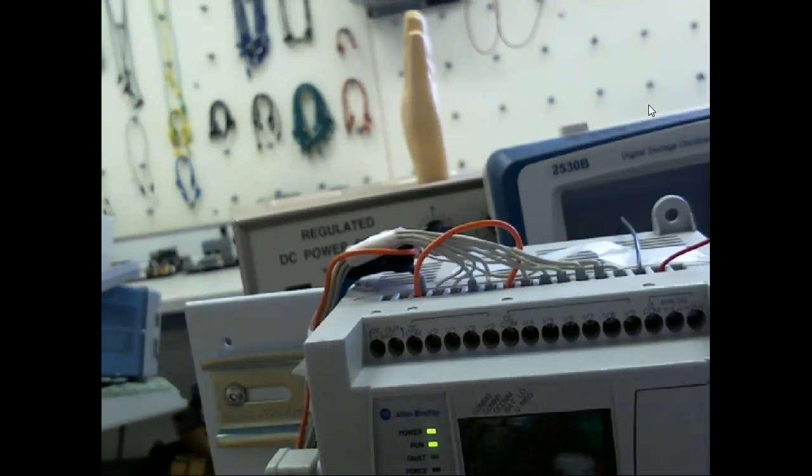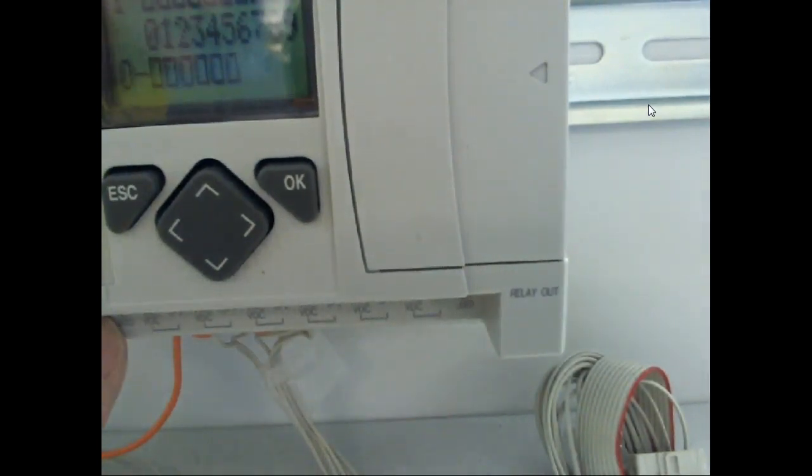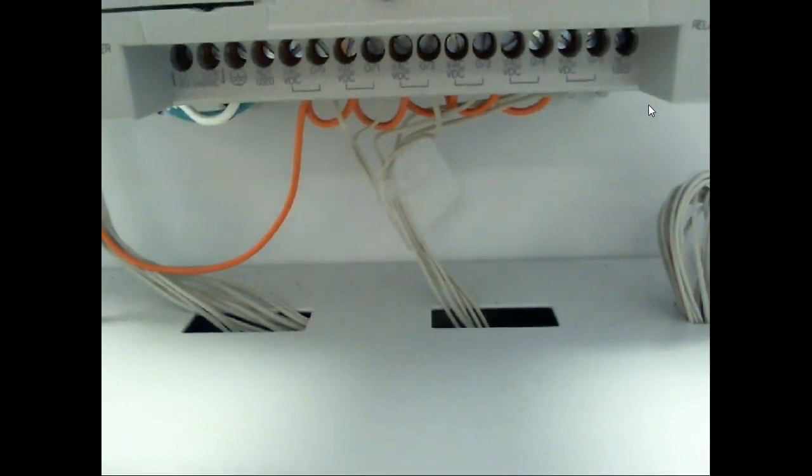Then when I come over here and look at my outputs, and this is going to be angled, guys, I'm sorry. Now this guy's got all kinds of commons on it because this is a relay output, which is pretty neat. Me and my camera. So notice what it's got. It's got DC, DC, DC, and it's also got AC on the top. This is real hard to deal with. There we go. So what's nice about relay outputs is you decide what common you want.